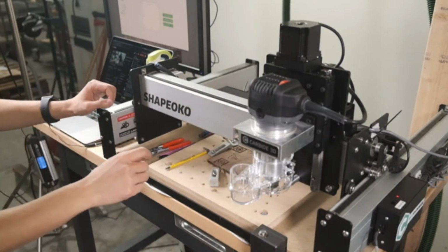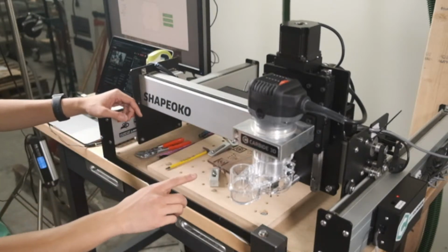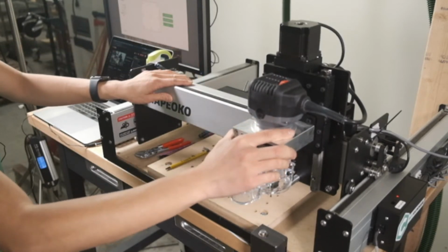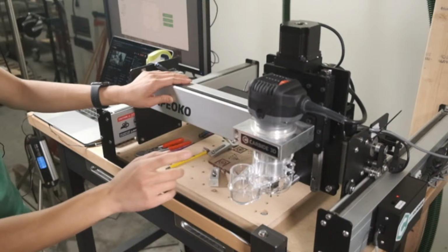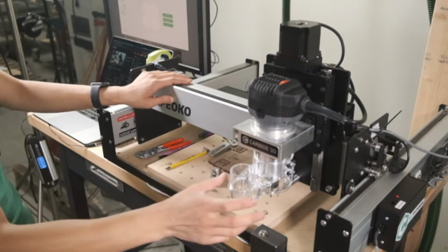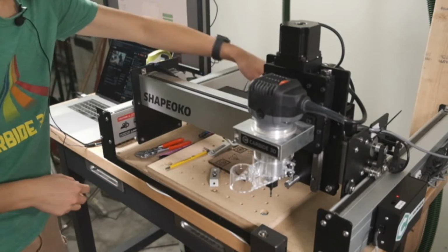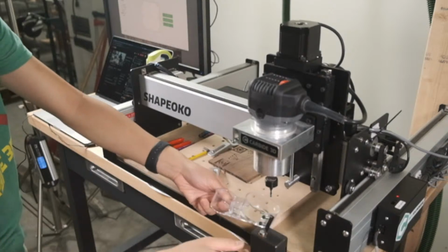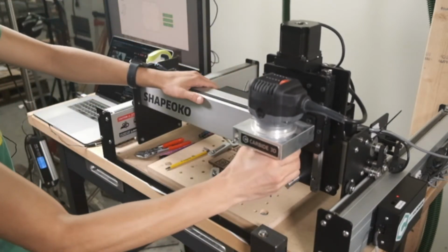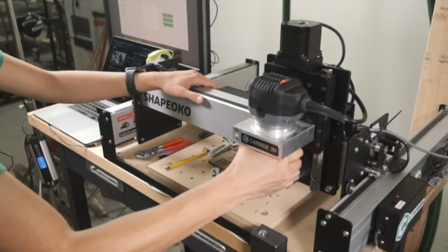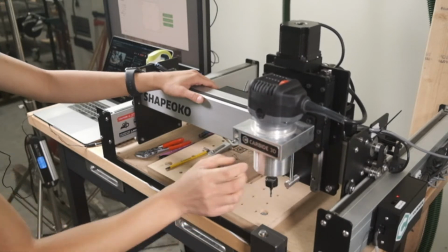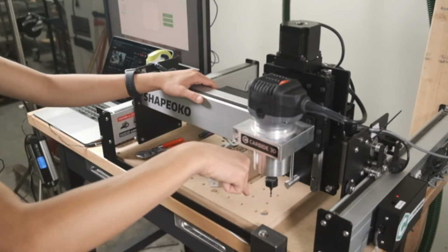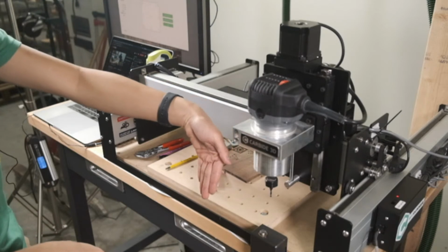So the other issues that can arise, we talked about why if your belt is loose, you might get backlash left and right. There are other conditions that would cause inaccuracy in your cut. So one of the other checks that I recommend is to just take your spindle and give it a little shake. If you hear any clicking or you see a lot of rattling, that means your V-wheels are loose. And this can cause a lot of issues just because the tip of the end mill is going to flutter back and forth as you cut.